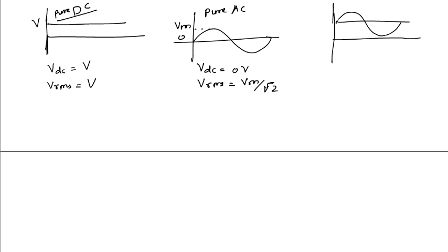This signal has 0 DC level, hence it is called a pure AC signal. For the third signal the DC value is not 0. The sinusoidal voltage is oscillating around this voltage V, and it is going up and down around this value by voltage Vm.